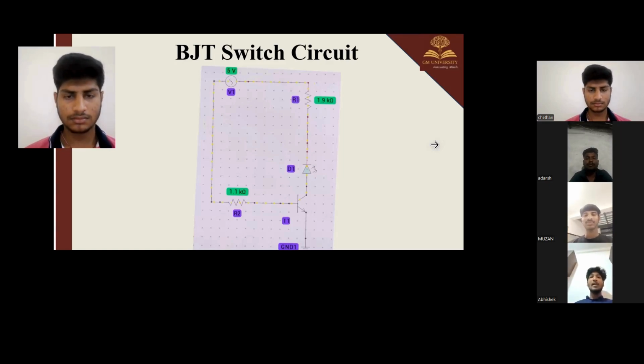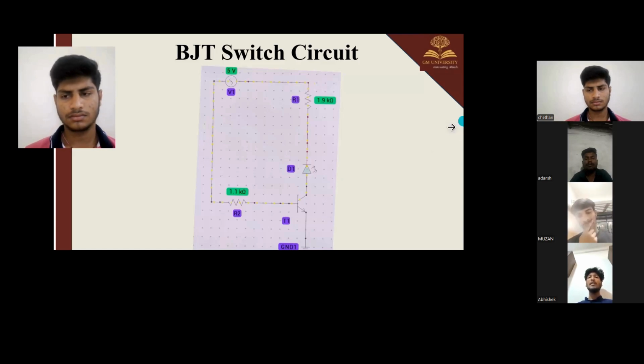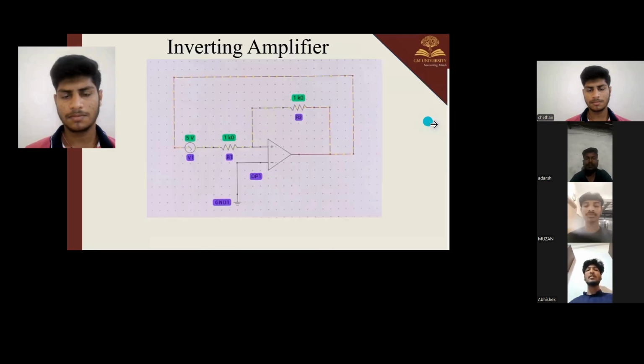An inverting amplifier is an operational amplifier configuration where the input signal is applied to the inverting terminal and the non-inverting terminal is usually grounded. Inverting means the output signal is 180 degrees out of phase with the input signal. In simple words, when the input goes positive, the output goes negative, and vice versa. The circuit is popular because it provides excellent stability with predictable voltage gain, high input resistance, and very good accuracy, especially when using an ideal op-amp.